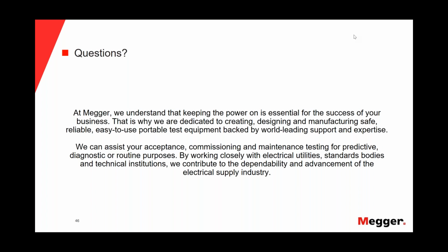I think the question, I would change the question a little bit and say it's not the matter of factory test 60 Hertz and field test 0.1 Hertz. In general the question is whether a 60 Hertz test, whether it's field or factory test, is technically a sounder test than a 0.1 Hertz PD test.